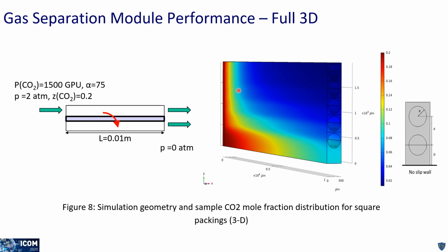What's shown here are the concentrations of gas, of CO2 in this case, within the shell, within the gas flowing around the outside of the fibers. What we can see is that in this region adjacent to the fiber wall, between the fiber wall and the first fiber, we see much higher concentrations of CO2. This channel right here acts like a bypass channel in which we have very high flow rates and reduced rates of CO2 capture. Well, from these simulations, we'll be able to assess the interaction that occurs between the fibers and whether this equivalent flow channel approximation is appropriate.